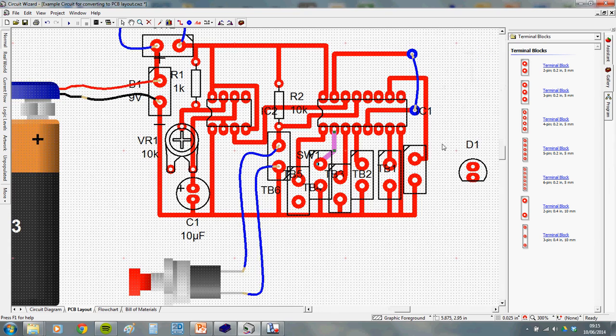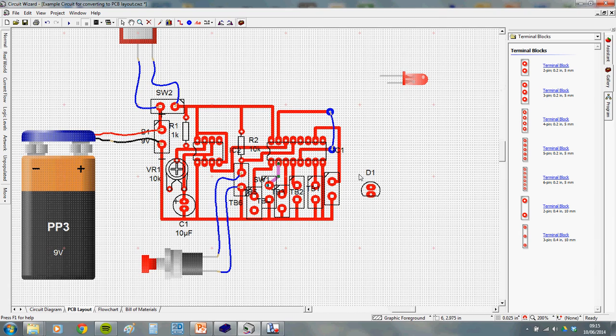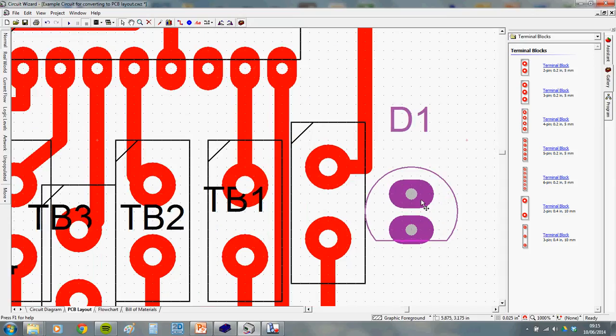Alright, there we are. The reason I'd like you to do that with LEDs in particular is because if you look at the size of the pads on a terminal block compared to an LED pad area, it's much easier to solder to this big round area than it is to these. The other benefit is they're spaced slightly further apart, and LEDs, if you put them directly on the board as this picture's designed to, they're very close together and you'll find the soldering iron will bridge them.